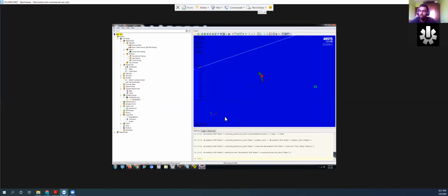So just remember that if you're having a multi-piece structure, like for example a seat, make sure that the direction that you're building up on all align to the same direction. Otherwise, you're going to have a weird thing where one half of it goes up and the other half goes down, and that's just going to create a weird point of weakness here. And it's not going to be able to solve during the mechanical analysis later when you apply a load, because there's no overlapping carbon fiber weave. So once that's done, you want to update.